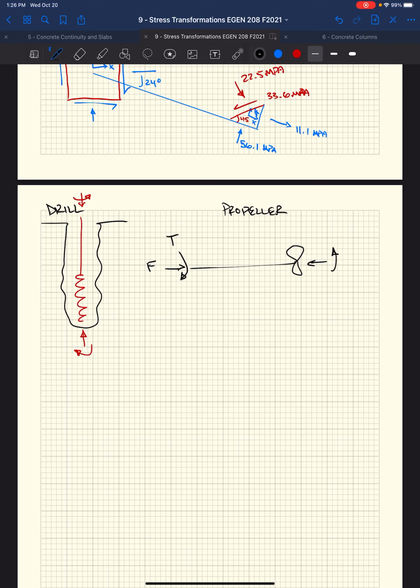You guys could come from power all the way back to figuring out what the forces are and the shear stress in the shaft. So we have this normal stress and a shear stress. Sigma is based on the force over the area. Tau is based on the torque times the max radius over the polar moment of inertia. So you guys are mumbling those equations in your sleep. Aren't you? No?